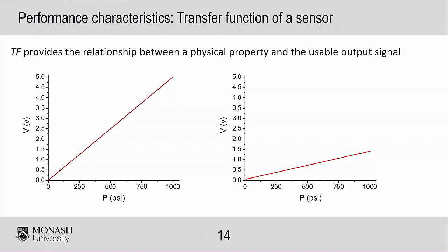Sorry? You'd have to change the gain and offset values. Yes. So the second one has less gain. So what would you do to the offset value? The offset value looks approximately the same to me, maybe just a little bit higher. You're exactly right. The only reason it's a little bit higher is because of my poor drawing in PowerPoint. So in this case, you would adjust the gain value for the transfer function. You would decrease the gain because the slope of the line is decreased. Quite easy, right? So then let's look at another case.